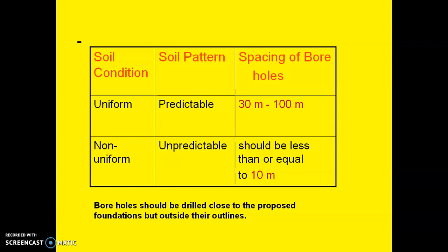On the contrary, non-uniform soil at every level will show unpredictable physical and engineering forms. Hence, it is necessary to drill boreholes at smaller spacing, that is, keep the borehole spacing less than or equal to 10 meter. Precaution to be taken that boreholes should be drilled close to the proposed foundation but outside their outlines.